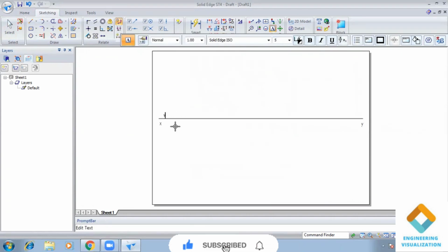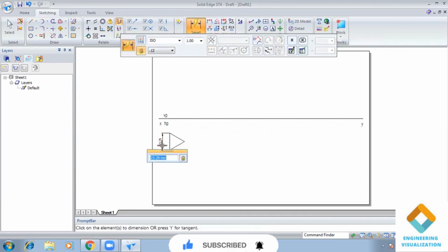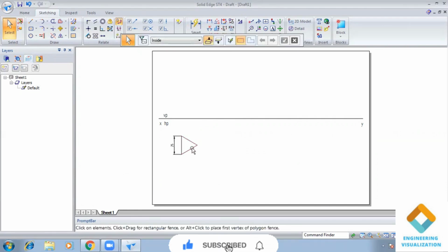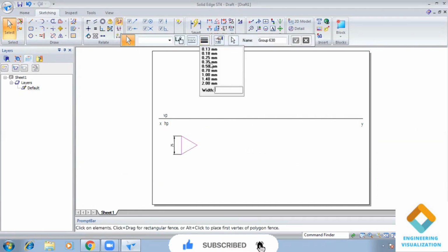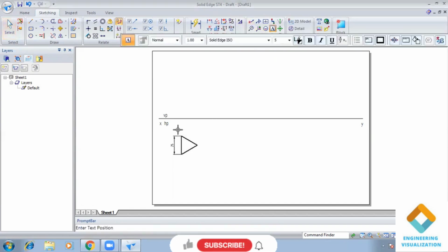So before that you mention VP, HP, X5. For this you will get 2 marks. To construct the triangle, go to polygon by center, give the number of sides as 3. Now place the lamina with respect to edge on the left hand side reference, and select the edge and give the dimension 25. So now we have drawn a triangle of dimension 25. Now change the thickness to 0.50 mm.